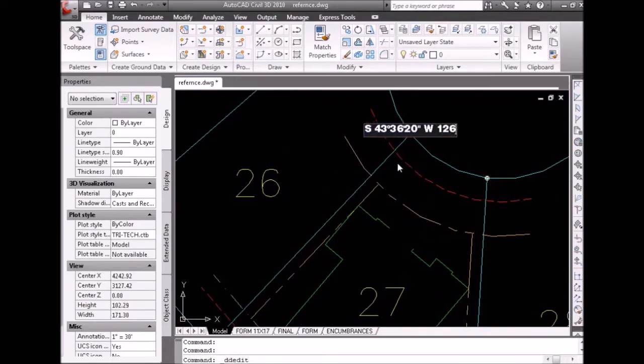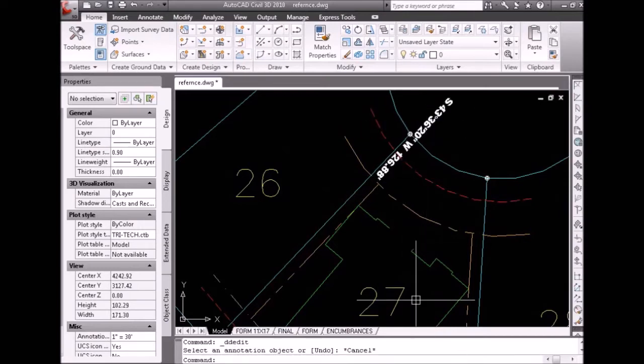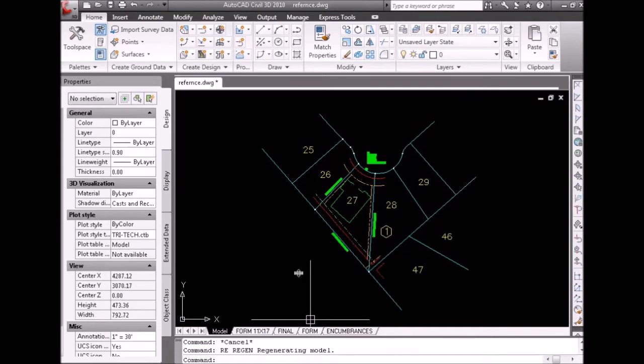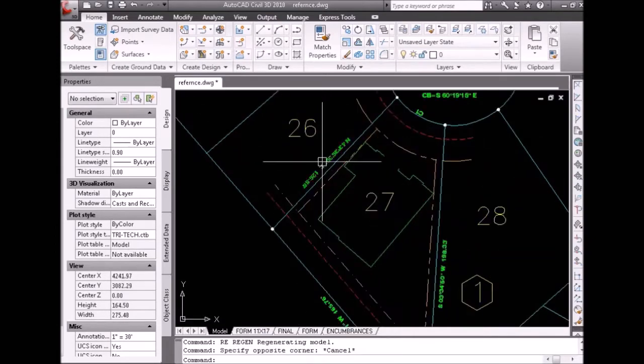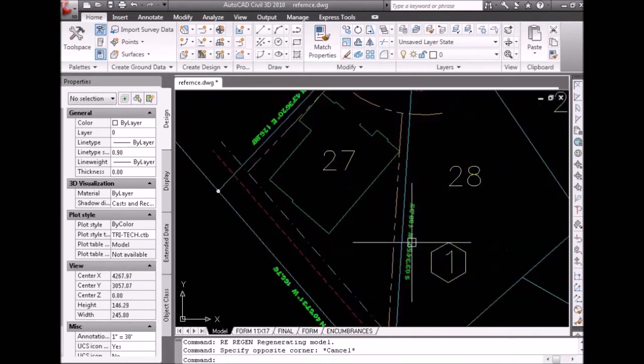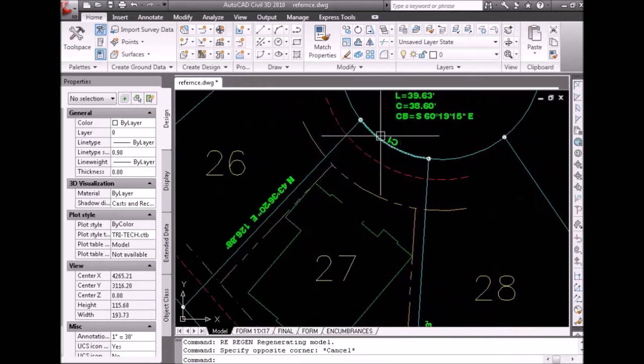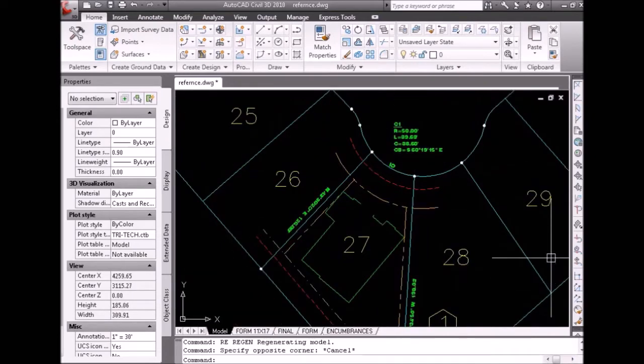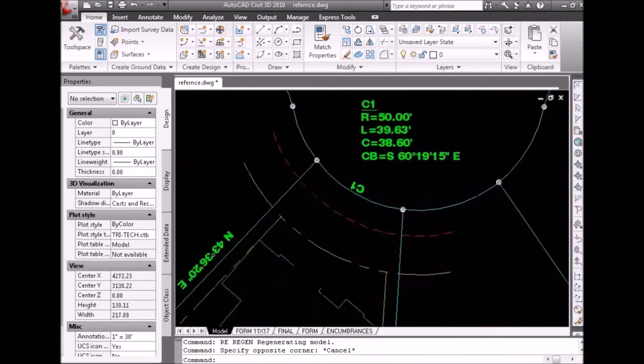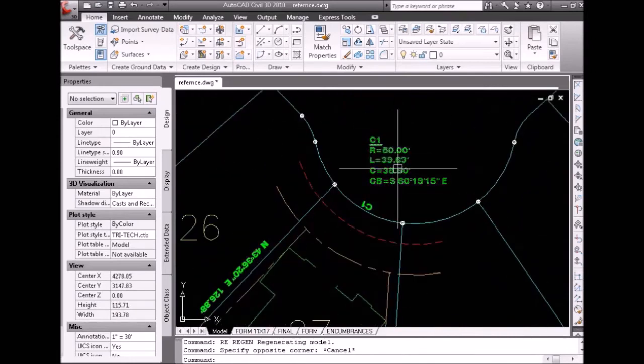Note the addition of the labels to each one of the sides is conducted and is now complete. Note that we have an arc in our lot. If our lot possesses an arc, we have to update details like radius, arc length, and chord bearing.